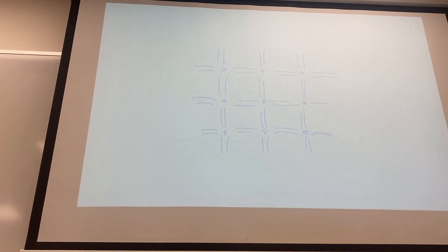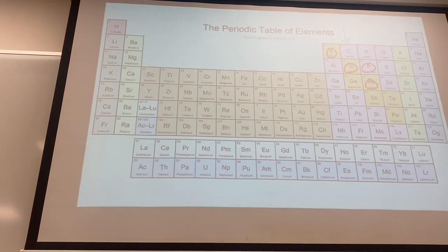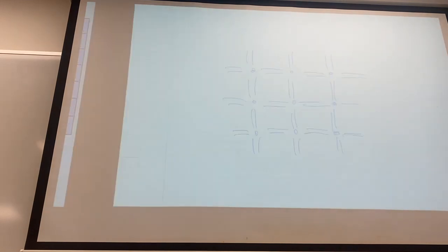Everything is stable, all the electrons are where they should be, they're not randomly bouncing around, and we haven't added any impurities. We haven't doped the semiconductor yet. And then what we do is we add some new thing. We fire in, we'll say, boron. We'll say this node in the middle is now boron. Boron is a group 3 element, so it's only got 3 electrons in its valence band.